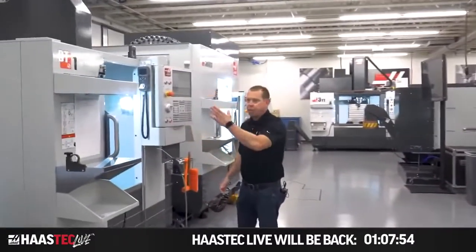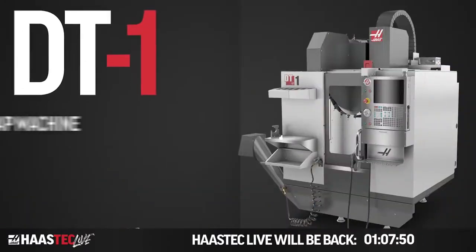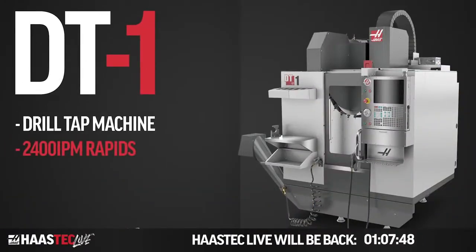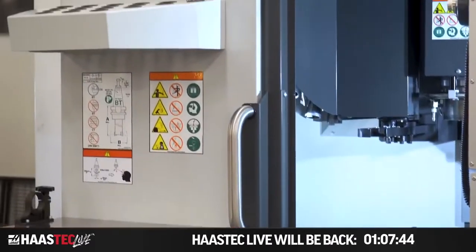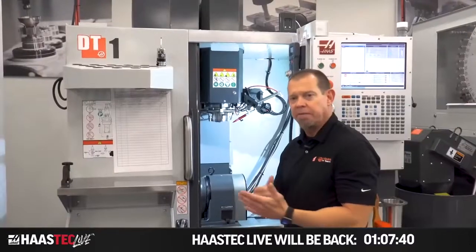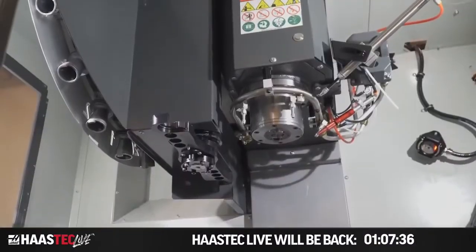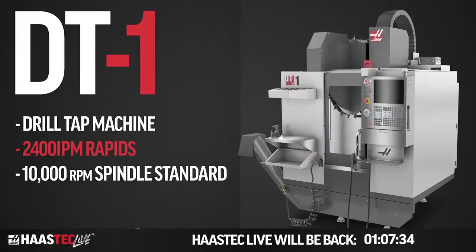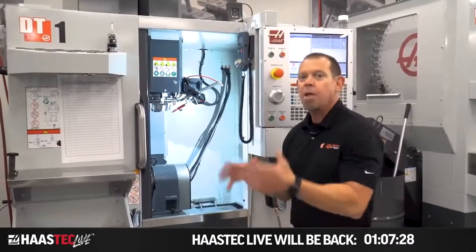All right, as Andrew said, right next to the VF2 SSYT, we've got the DT1. Now, DT stands for drill tap. This is a super fast little machine, 2,400 inch per minute rapids, tool change in under a second, but it's got great milling capability too. It's got a 15 horsepower spindle. Speaking of spindles, 10,000 RPM is standard. We've got 12, 15, and 20K optional. So if you're drilling a lot of small holes and you want that high RPM, you can get it with this machine.